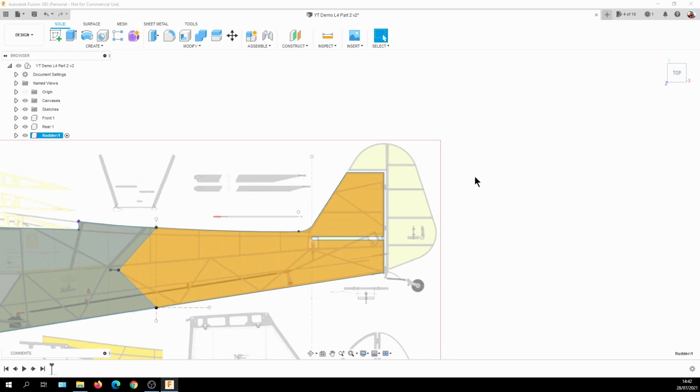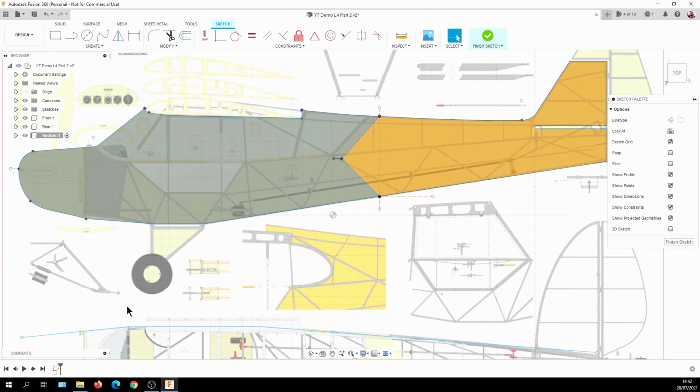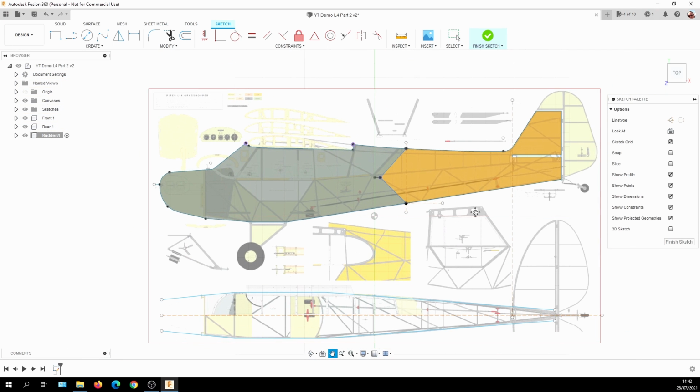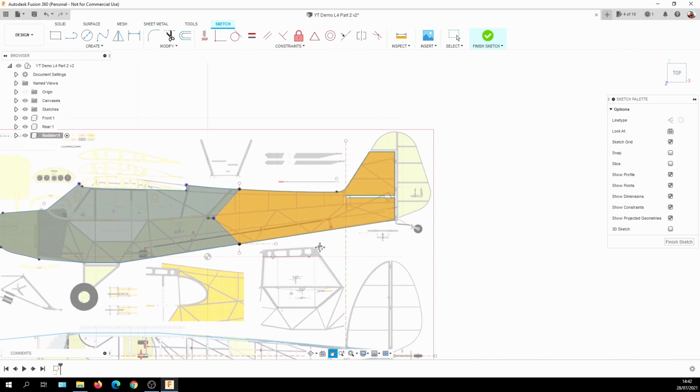component. What we want to do is trace around this. So we're going to create a new sketch. And it's asking us which plane. You can just see that there. So we've got the top. I always do everything off the top plane. It tends to make things a bit easier, especially when we go into the drawing section. Right, so we'll just move this across.